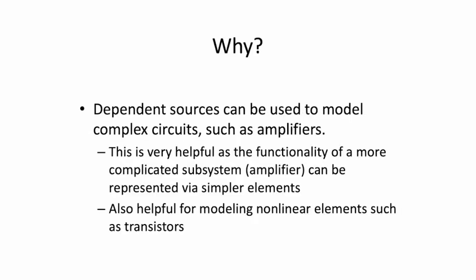Now, why do we need these devices? Why would we want to do this? Well, dependent sources can be used to model complex circuits such as amplifiers. This is very helpful as the functionality of a more complicated subsystem, like an amplifier, can be represented via simpler elements using the dependent sources. This is also helpful when modeling elements that are nonlinear in nature, such as transistors.